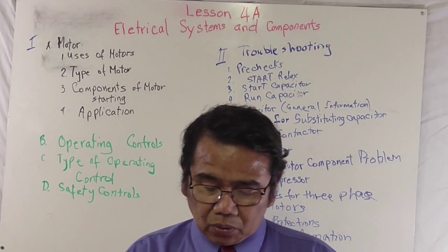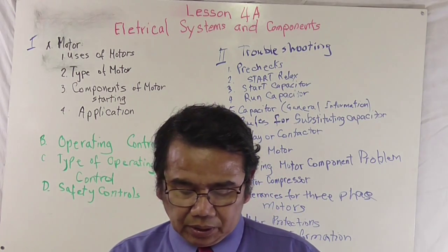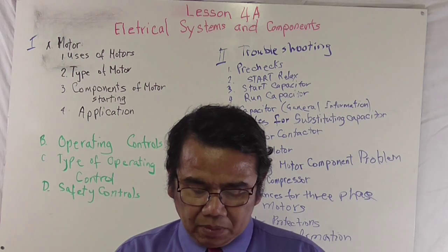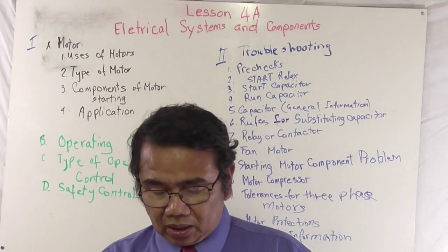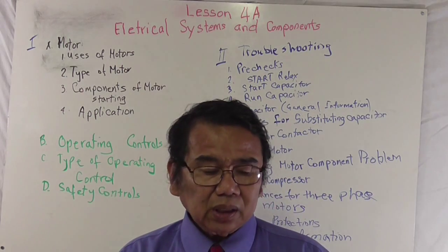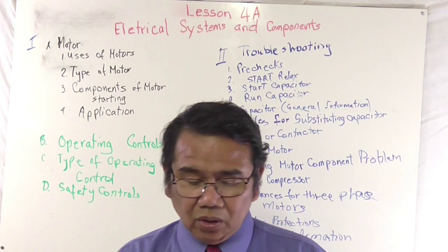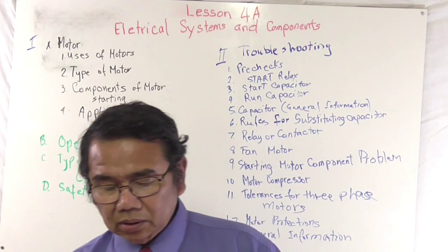Compressor must be cooled below 115 degrees, okay, before making continued checks. Ensure the internal protector is closed. Never jump across the compressor terminals of an internal thermostat.